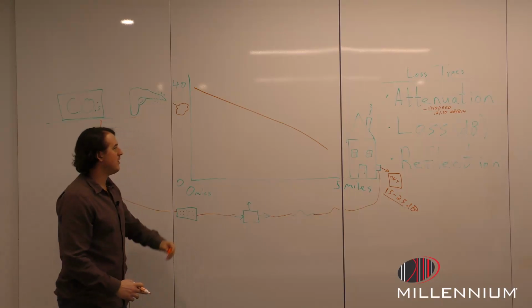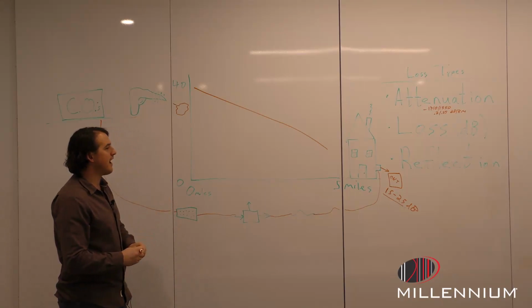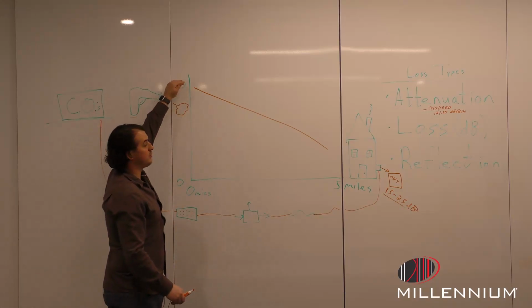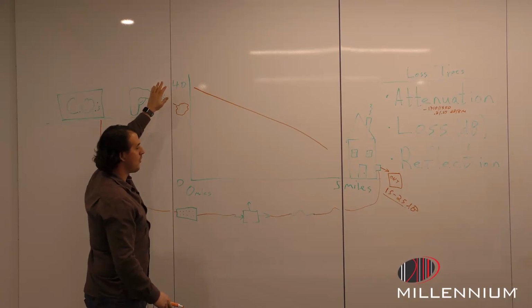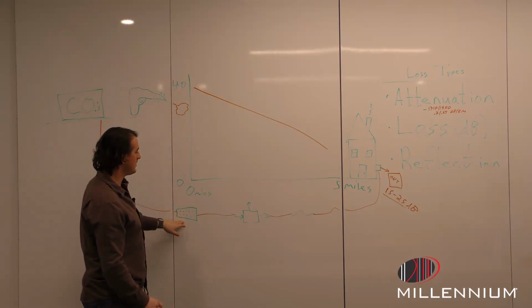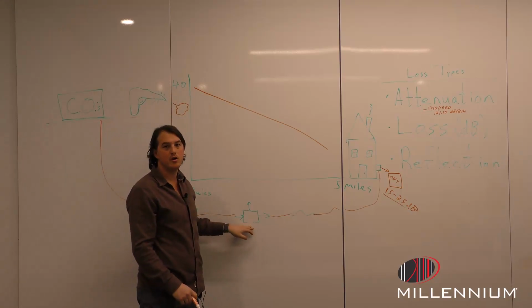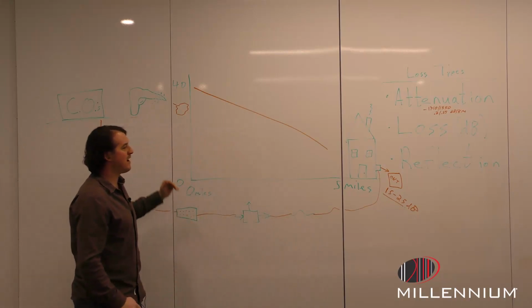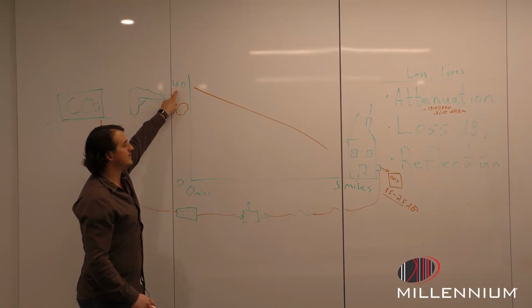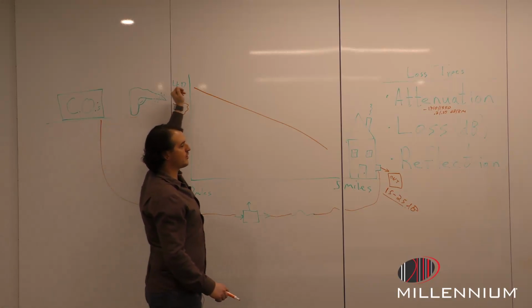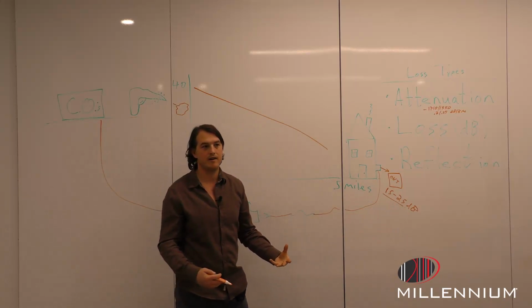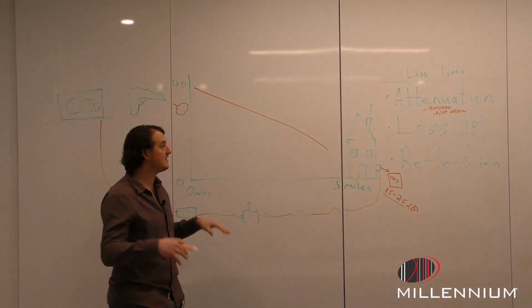So a lot of engineers are going to put together a light loss plan. As they start adding components, figuring out where handholes or splices should go, we start measuring. Our lasers are going to inject 40 decibels. At the house, we need to end up between 15 and 25. Okay, cool. Let's dive into this.